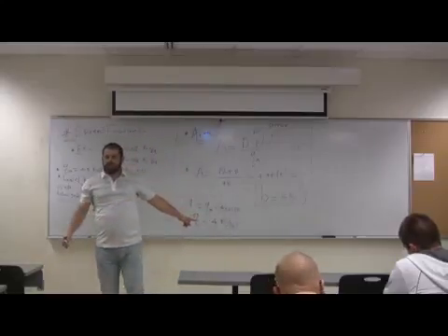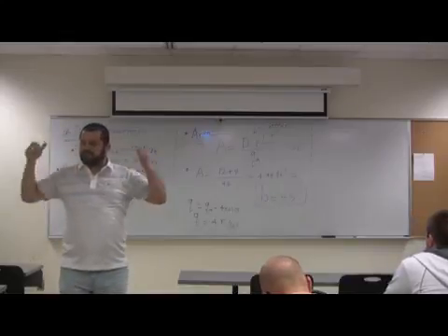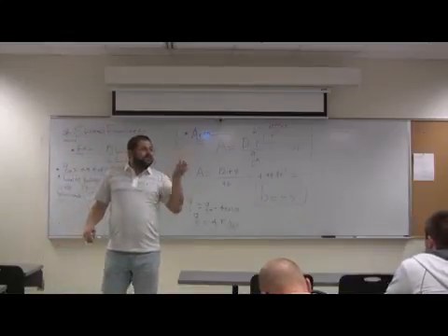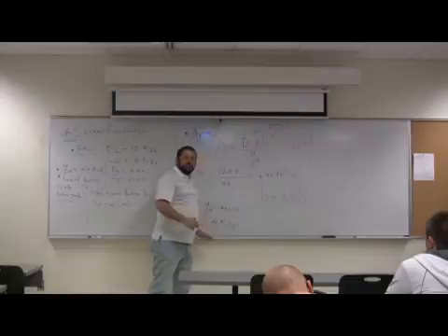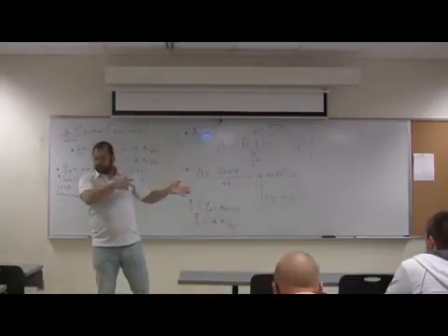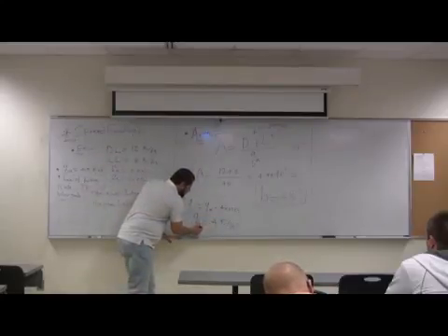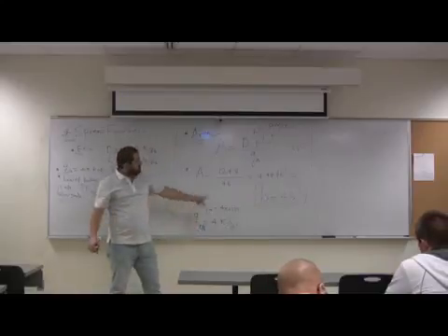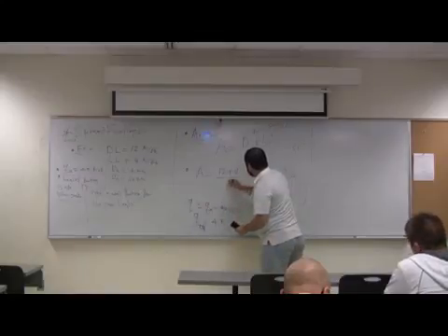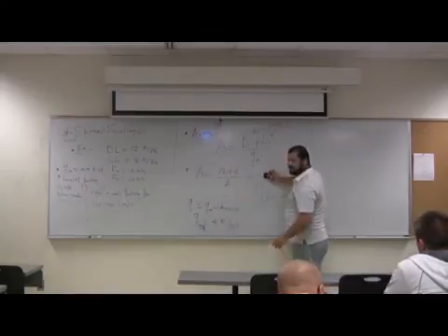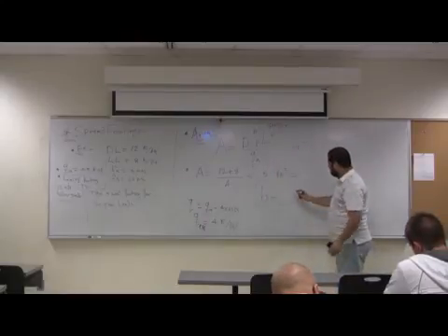What do you want to call it now? What we are doing is the effective. This is the effective for supporting the load. Part of it went to support the soil and the self-weight of the footing. Again, as I told you, you can calculate those as weight and add it to the dead load if you want, the self-weight and the weight of the soil. So this is Q effective, QE. Now this will change here. This will be 4, and you give me this number in here. 5? Exactly 5? Well, it's 20 over 4. Yep, so that's 5. We're going to use 5.